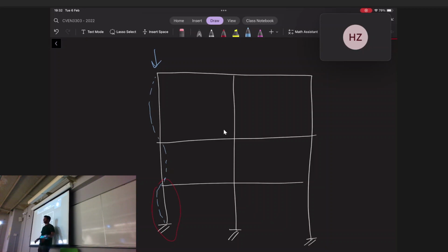In the previous example, I gave you a really simple case. The bottom is imagined as a pin, and the top is imagined as a pin. That's a really, really simple example because it'll just bend perfectly. But when everything is interconnected like this in a real life building, that's not how it's going to deform, because the deformation here is linked with the deformation of every other element.